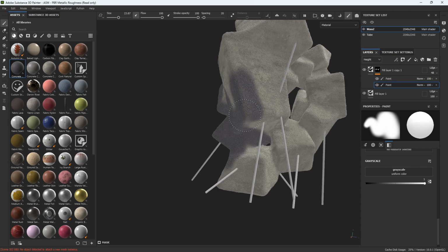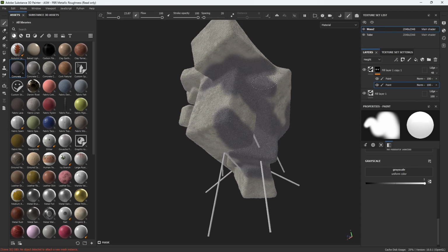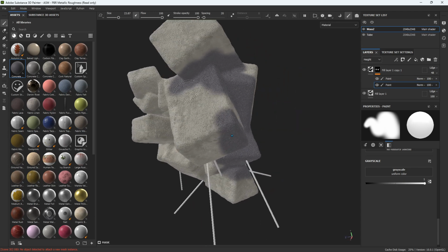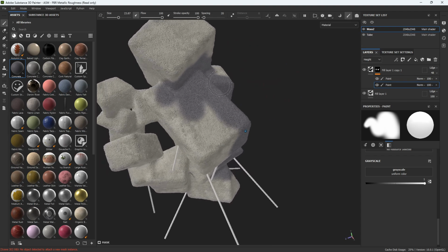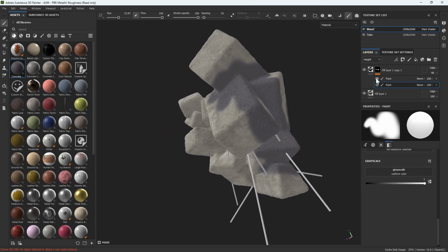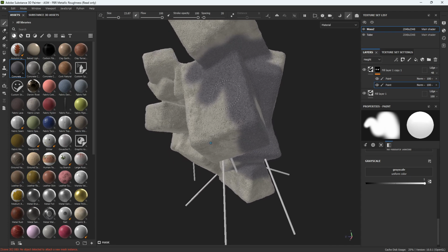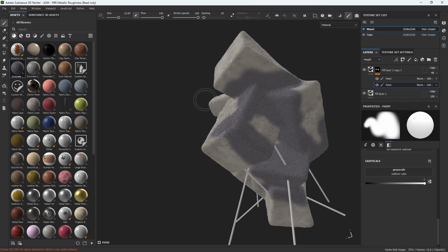This is why fill layers are really handy, because they give you a lot of control over how the painting happens. It's more of a non-destructive workflow, and one that you can quickly change and experiment with, like adding and subtracting. Right now I've just been painting white and adding this away. If I want to remove stuff, I can remove this material. I can hit X, and now that is being removed. And then X again will invert the brush back to white. And that is working well.